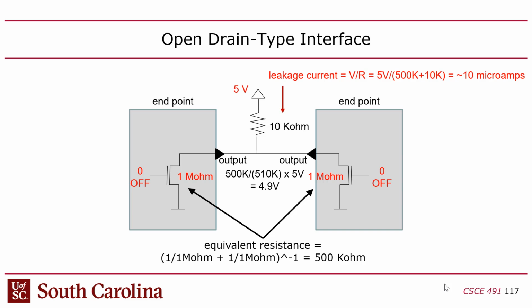And then normally with an I2C, there is some kind of collision detect because it's a multi-master bus. So any host can take mastership of the bus. There is a chance that you'll have two things try to simultaneously take mastership, in which case there's a collision. And if a collision happens, you have to back off. Generally speaking, if you have a hardware I2C interface, that collision detect is built into that. So in other words, it has to monitor what's going on as it tries to pull the channel low. In this lab, you don't have to implement that. You can assume that you're not going to have any collisions, right?